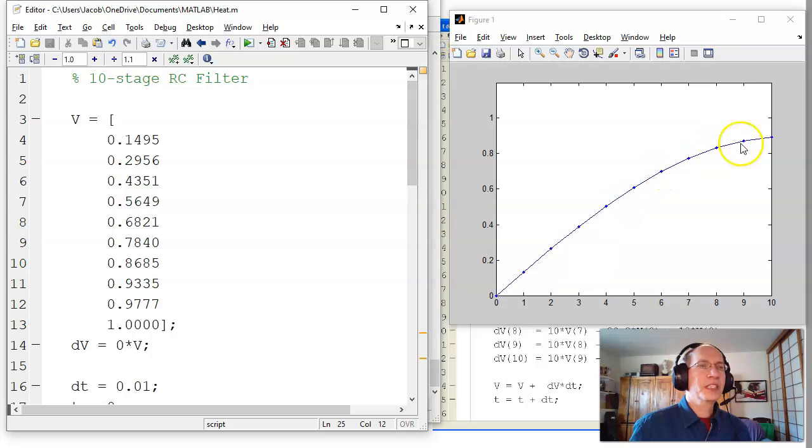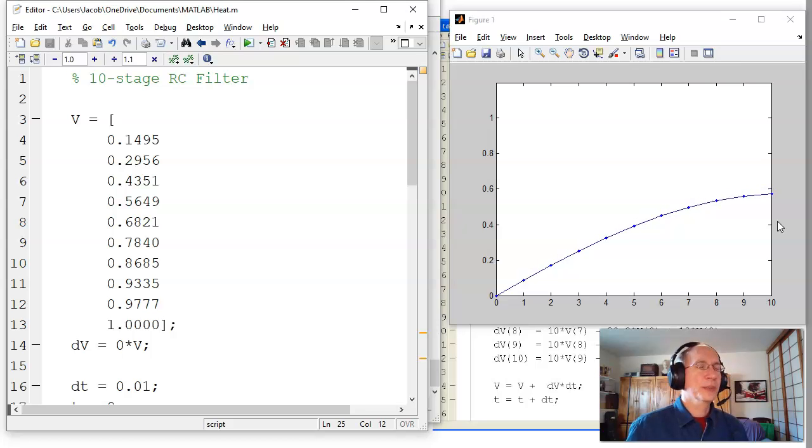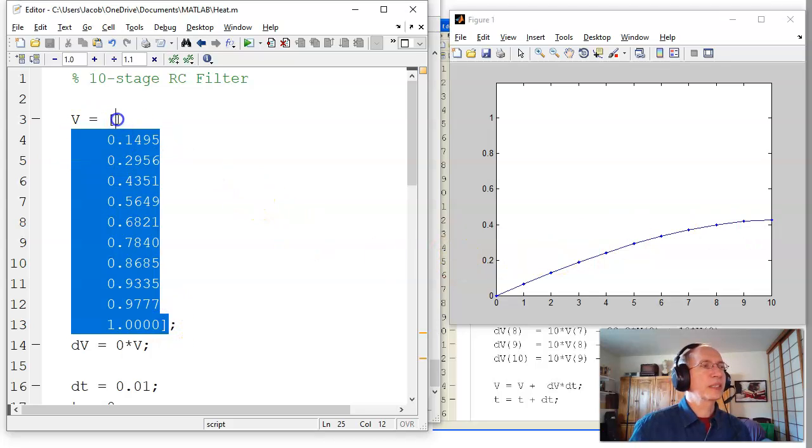You can see the shape stays the same. The shape is the eigenvector. The amplitude is dropping, however. This is dropping as e to the minus 0.49t. So that's the slow mode. And there's also 8 other eigenvalues, eigenvectors. Here's a question for you then. Suppose my initial condition is something random. What happens?